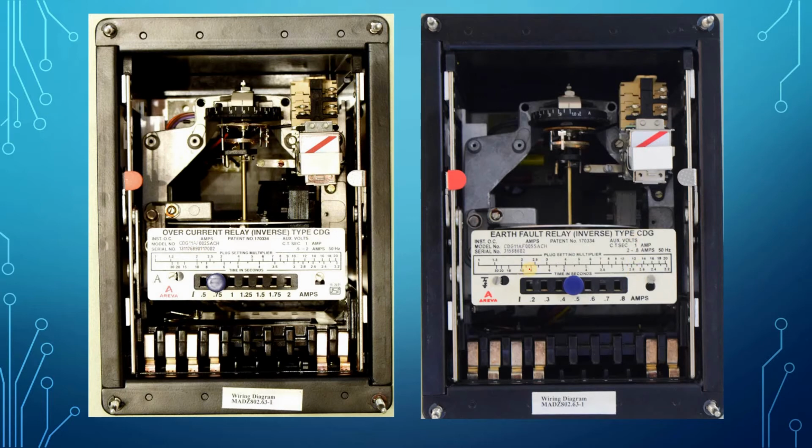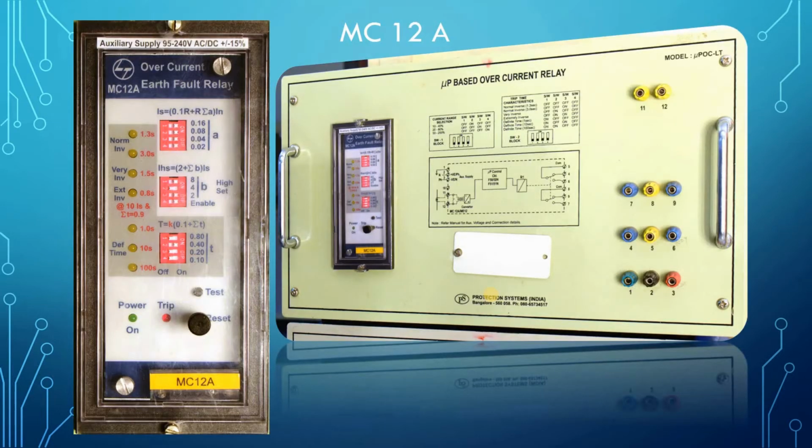But in case of numerical relay, all these three things are combined into one. And another thing, here at 10 times current we are getting 3, that's why this is the normal inverse 3 characteristic. Here also at 10 times we are getting 3, that is the normal inverse 3 characteristic. Similarly, Alstom also manufactures normal inverse 1.3 characteristic at 10 times. So these different types of characteristics are useful for different types of load and different types of fault. That is a separate chapter.